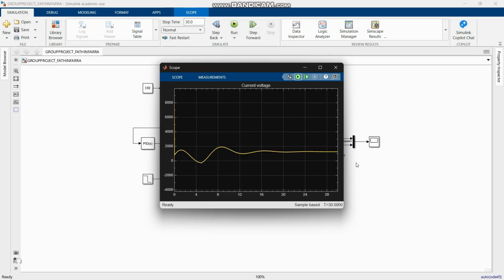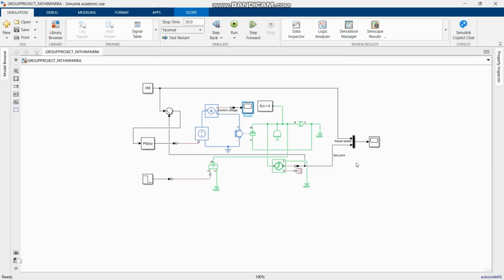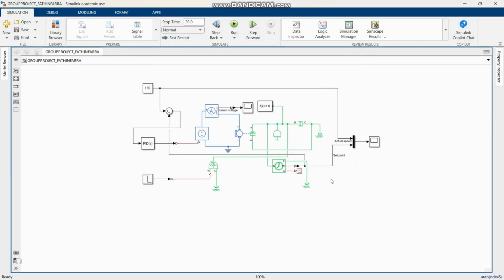Zero crossing detection helps Simulink accurately detect the exact time when the disturbance changes at 5 seconds. This is important because the disturbance happens suddenly and the simulation needs to capture the transition response correctly. The model runs successfully without solver errors or convergence problems.